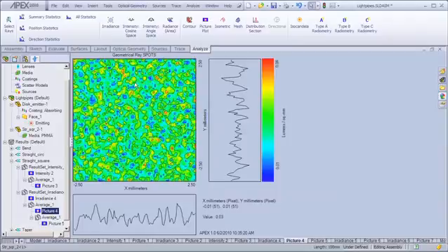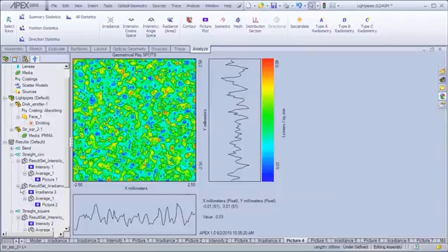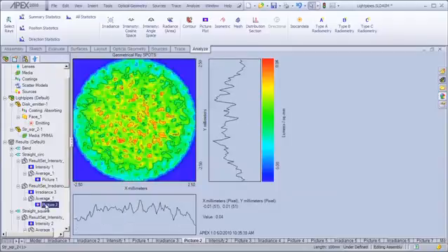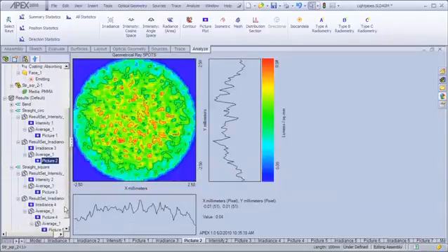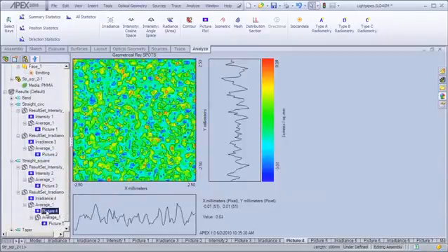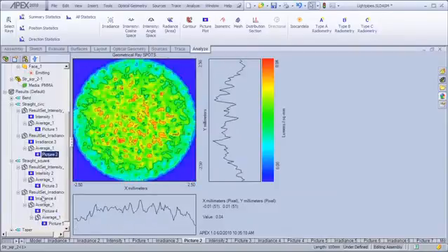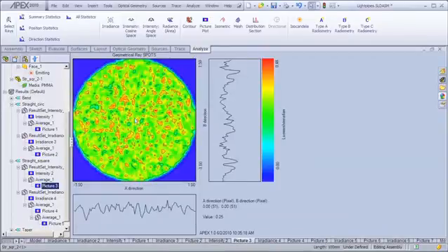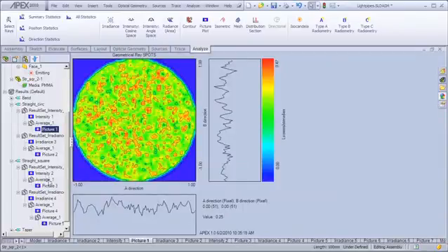And you'll notice that our energy distribution is a bit more uniform for the square cross-section than it was for the circular cross-section, so let's take a look at them. And in both cases, we've applied a simple adjacent pixel averaging to take care of statistical type noise or shot noise. And here is the intensity distribution in direction cosine space for the square pipe, and again we can compare that to the circular pipe.